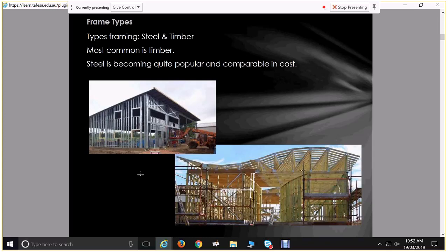Another big difference between timber and steel is the way it will behave in a house fire. Timber will maintain a structure in heat. You can get timber really hot and it maintains its structure, and as it burns through, it gets weaker and weaker, as the charring gets closer, because your structural cross-sectional area with timber is the uncharred amount. So as it gets burned more, it gets weaker. But steel, you get that to a certain temperature, it just buckles and gives in. So there's differences in the way that it will behave in a fire.